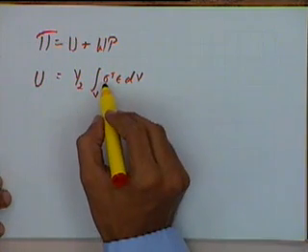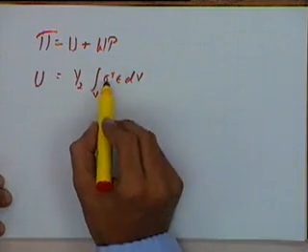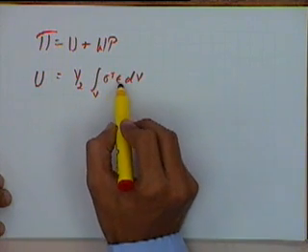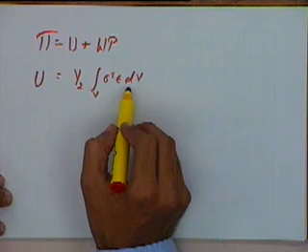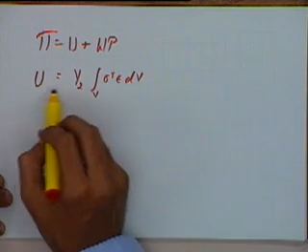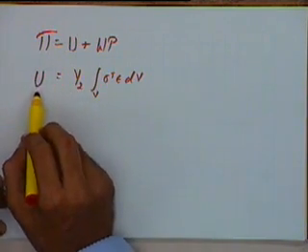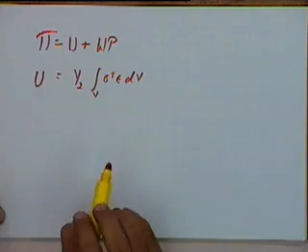That means if we take the transpose of the stresses, multiply it with the strain vector and integrate that over the volume, then half of that will be the strain energy.